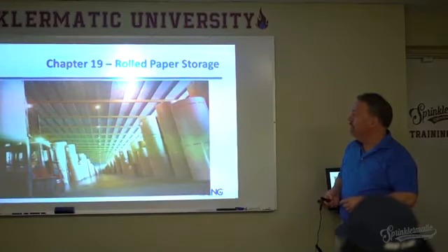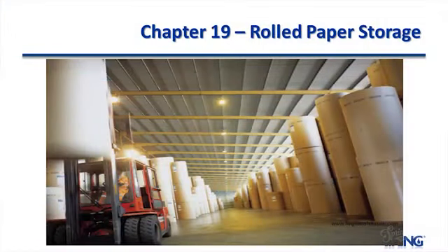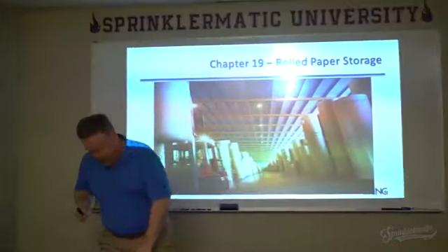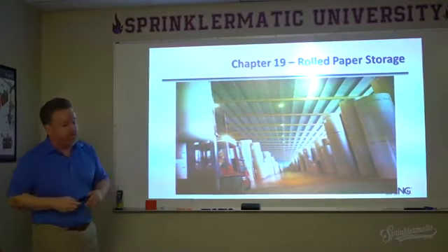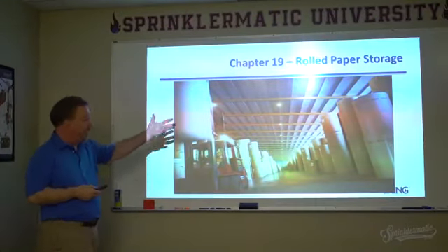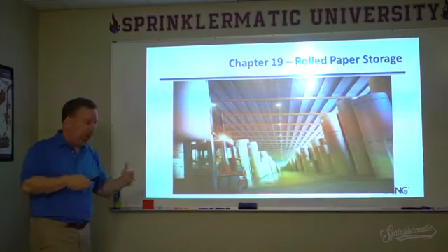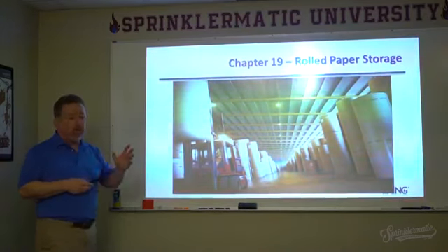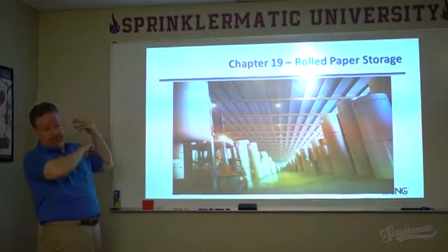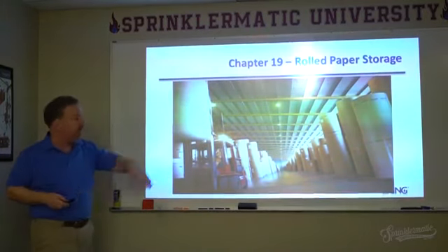Chapter 19 addresses rolled paper storage. This chapter in and of itself has not changed much at all over time. But basically, if you're protecting a rolled paper storage warehouse area, you don't use Chapter 16, 15, 14, whatever it is. You go right here to Chapter 19.